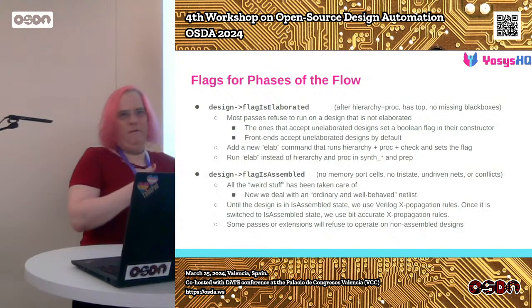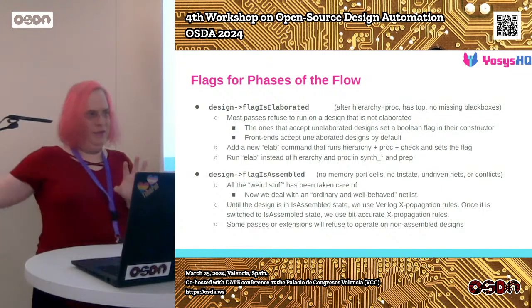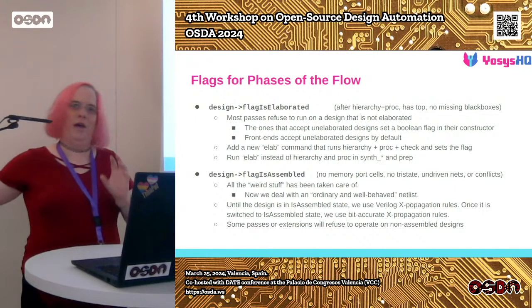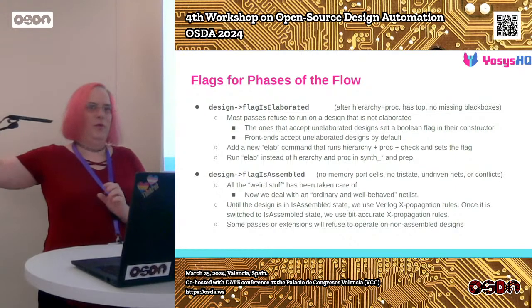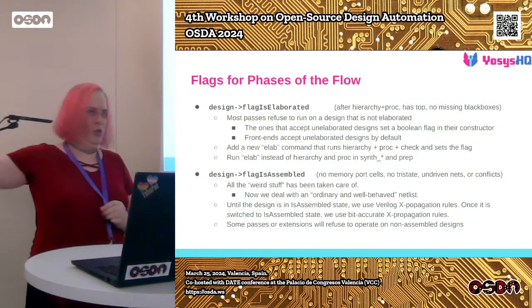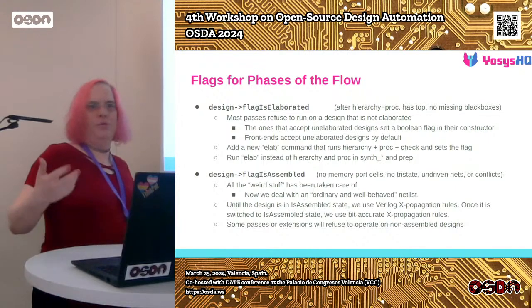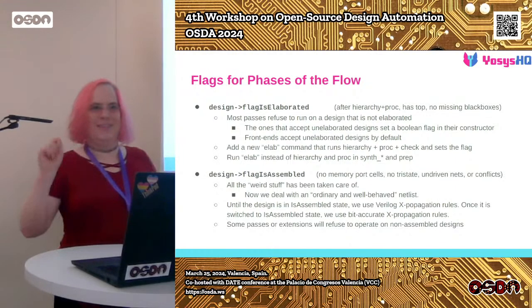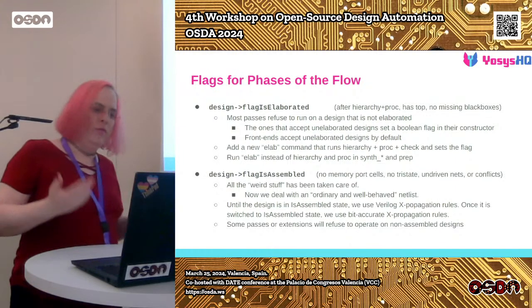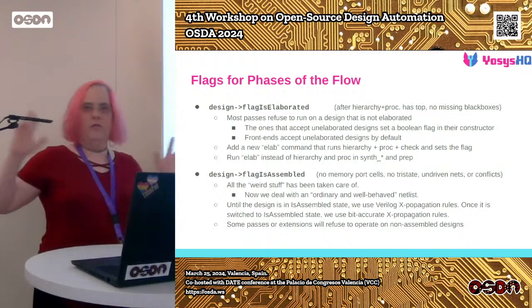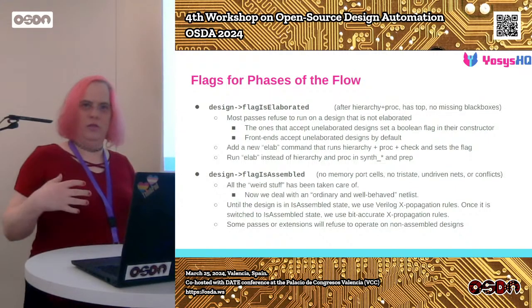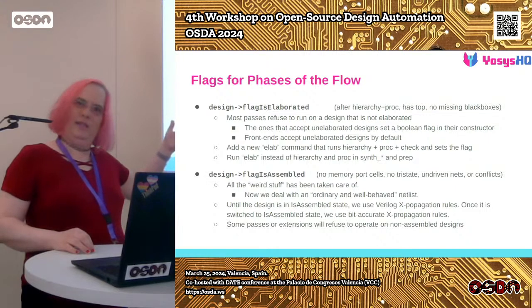And once the is-assembled flag is set, we do not run this high-level language-aware X propagation again, but now we run optimization passes that perform optimizations that are not preserving with respect to the Verilog X propagation rules. This is also something where these optimizations all exist within Yosys now, and there are additional options, but that's for most users not really obvious. It's common for so many flows using Yosys that it makes sense to deal with these issues in a more central infrastructure